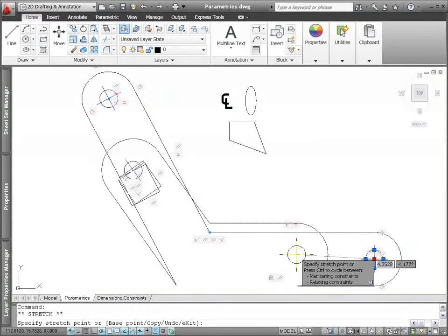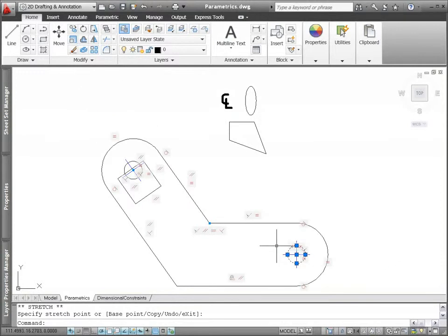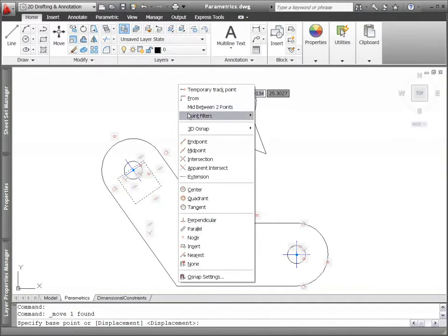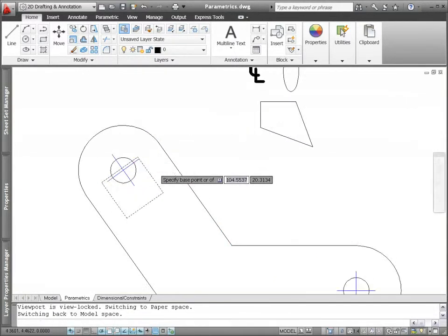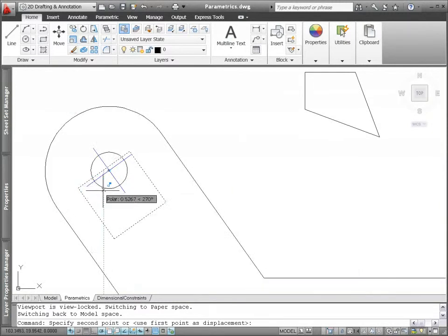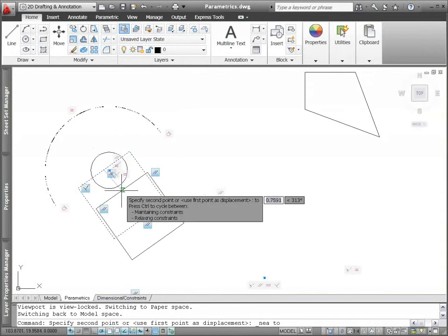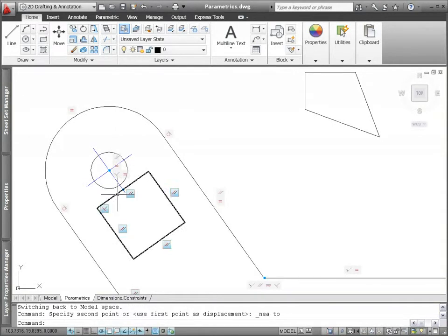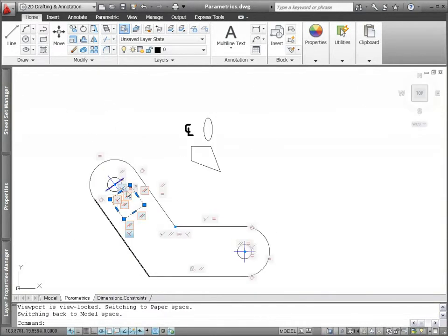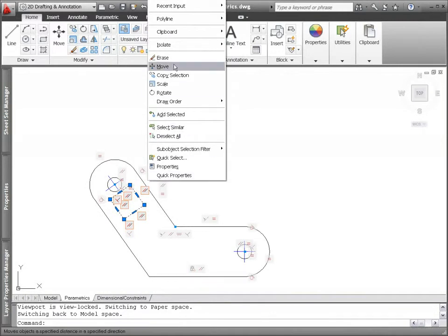In addition to creating point-to-point coincident constraints with specific object snap points, you can use the nearest object snap to apply a coincident constraint between a point and an object. For example, if you move the midpoint of the rectangle to the nearest object snap of the center line, the rectangle has the flexibility of moving anywhere along the center line, including its virtual extension.